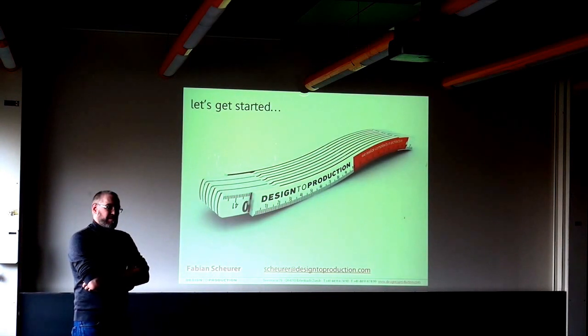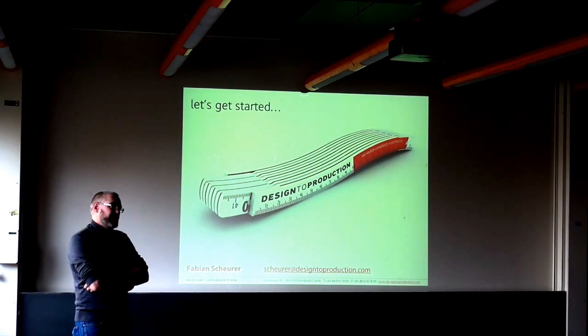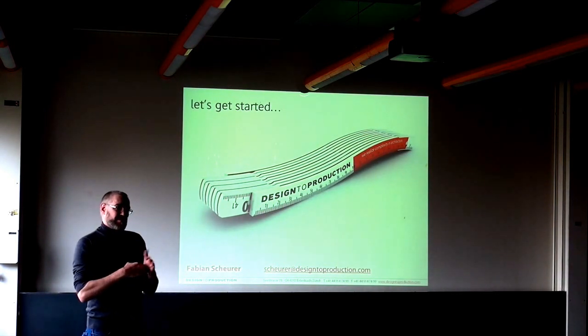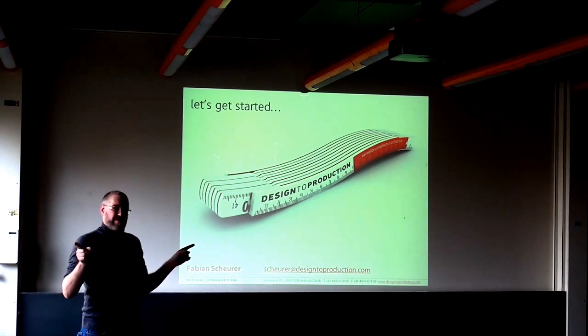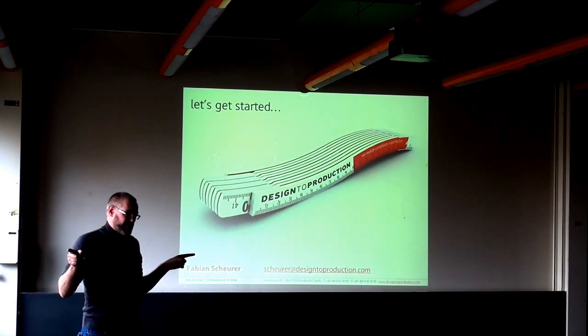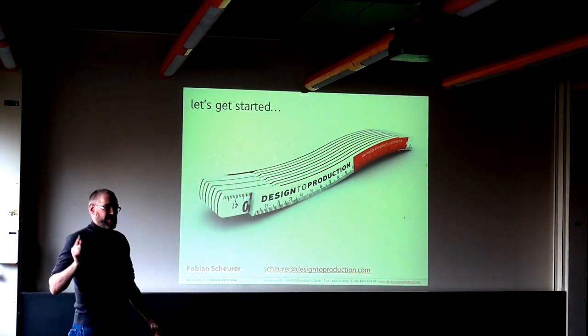Because someone, while doing this in an orthogonal way on a 2D drawing, has completely forgotten that two things are not orthogonal to each other in real life, and suddenly you can't engage the joint anymore, because the engaging direction of 2 neighboring joints is not parallel. That means you can drive it in here, you can drive it in there, but you cannot drive it in at the same time in both places.